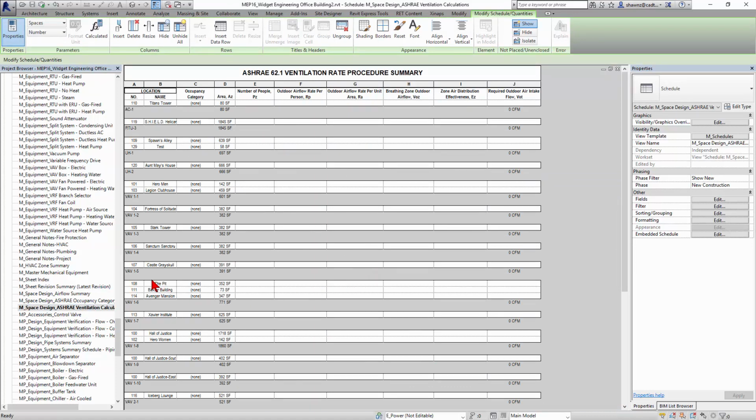Down here, one of my zones that I've configured, in this case happens to be a VAV box supplied zone, but I can actually take all the VAV boxes or all the zones labeled after certain VAV boxes connected to a certain air handling unit and get their totals as well. In this case, what I'm going to do is take this one zone specifically and tell it what categories of occupancy I have in these individual spaces. I'll do this one here live in front of you.